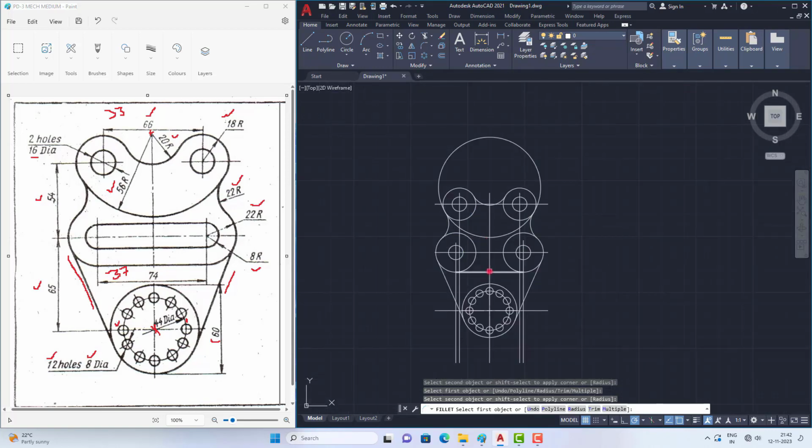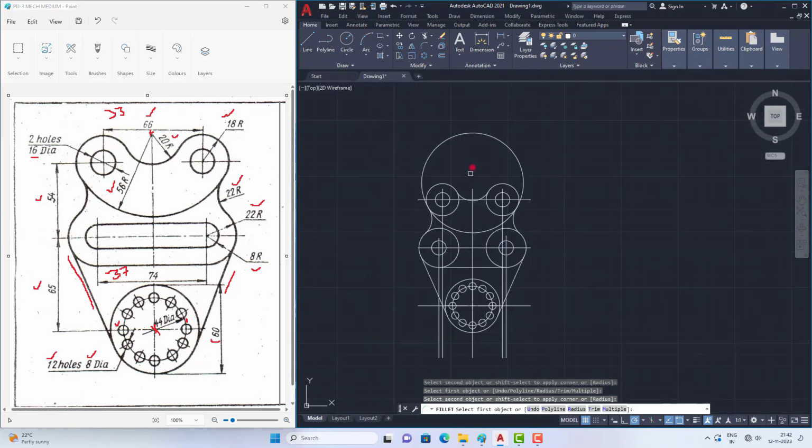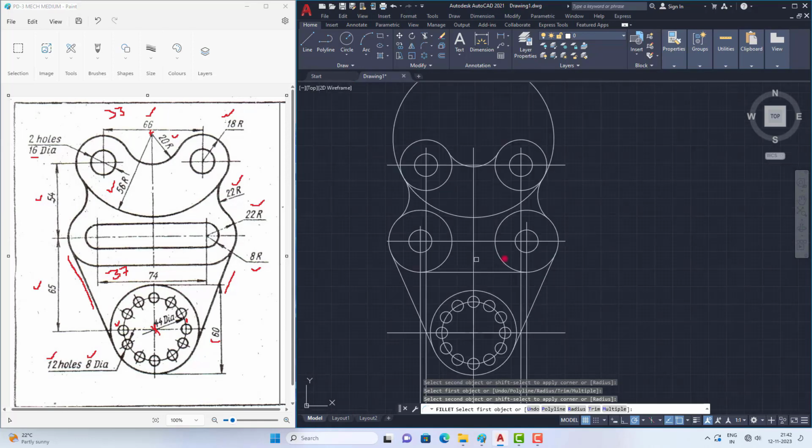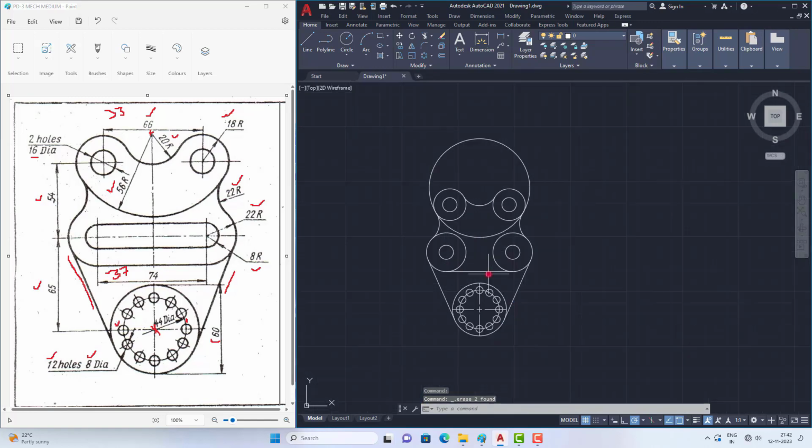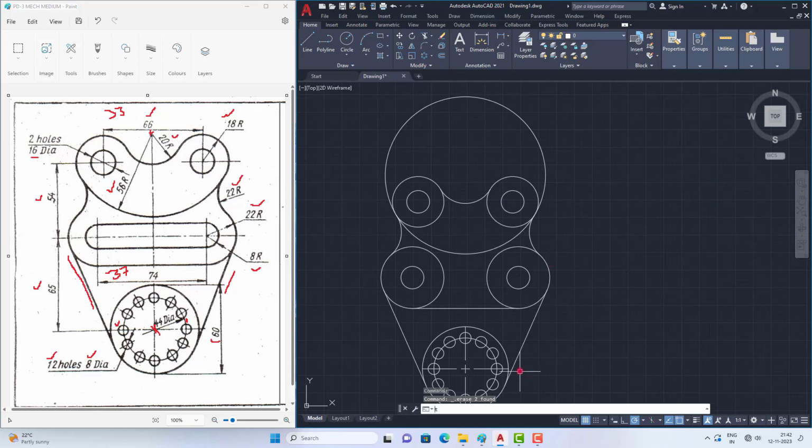And now remove the unwanted parts from this drawing. So these are the reference lines. So I am removing each and every reference line, because those will be confusing. So I am deleting that. And now check whatever you don't need and remove everything. Give the command tr and press enter a couple of times and remove the unwanted things.